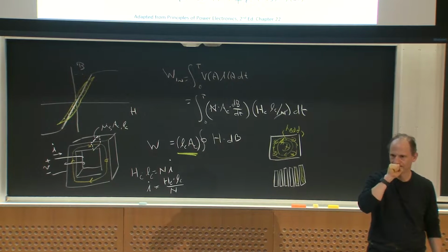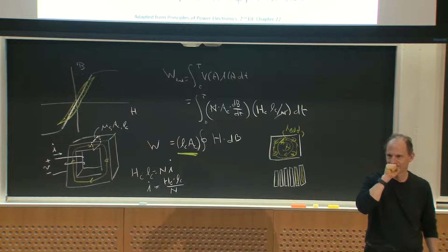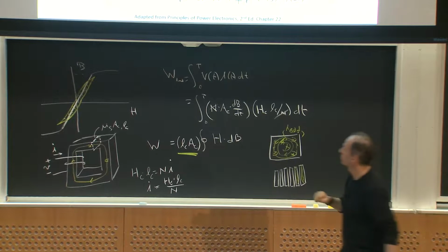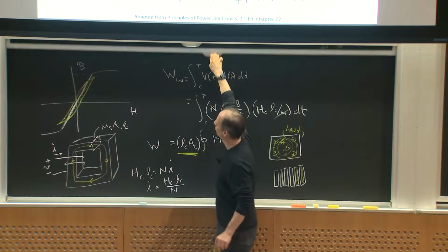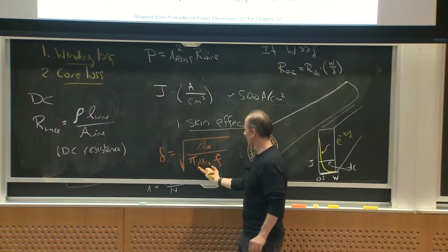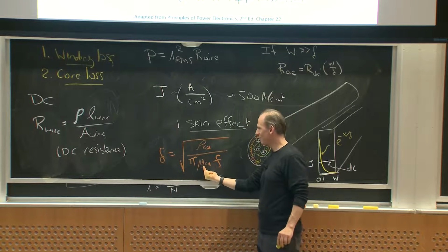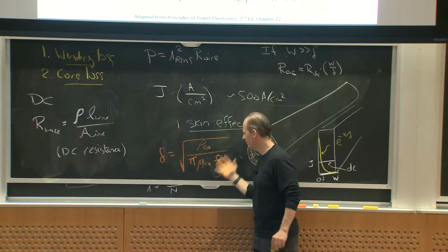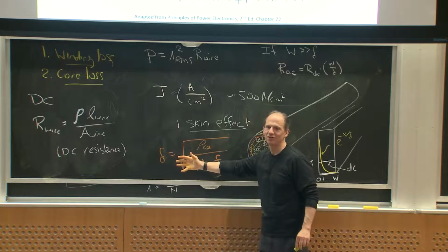Does it characterize a magnetic core as being higher or slower frequency? Like, is it related to permeability, or is it some other property? Well, it comes down to what's the skin depth. If you have high permeability, the skin depth gets small, right? So you just plunk this in and find out what is the dimension that I would care about.